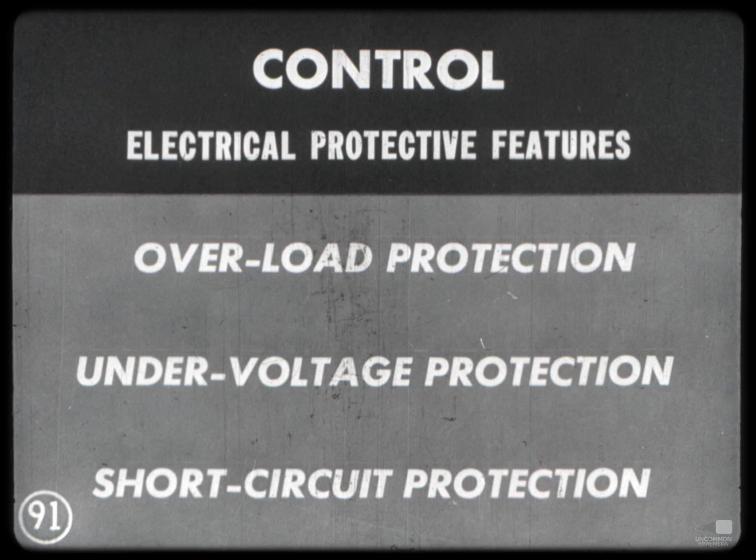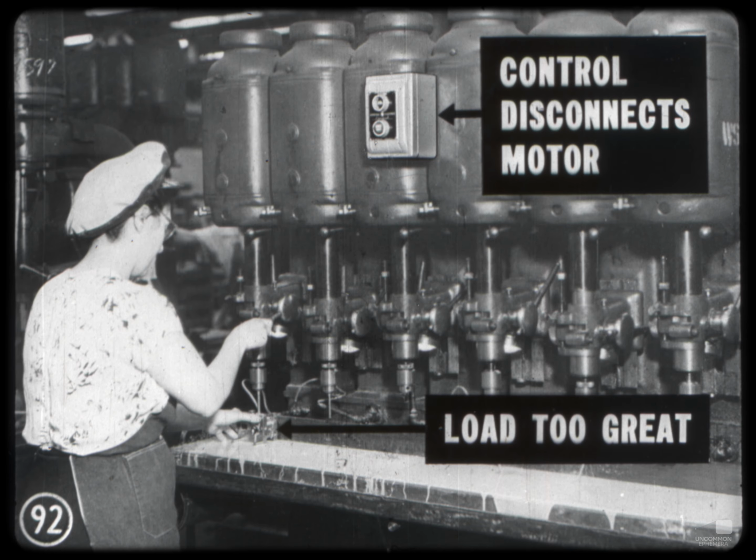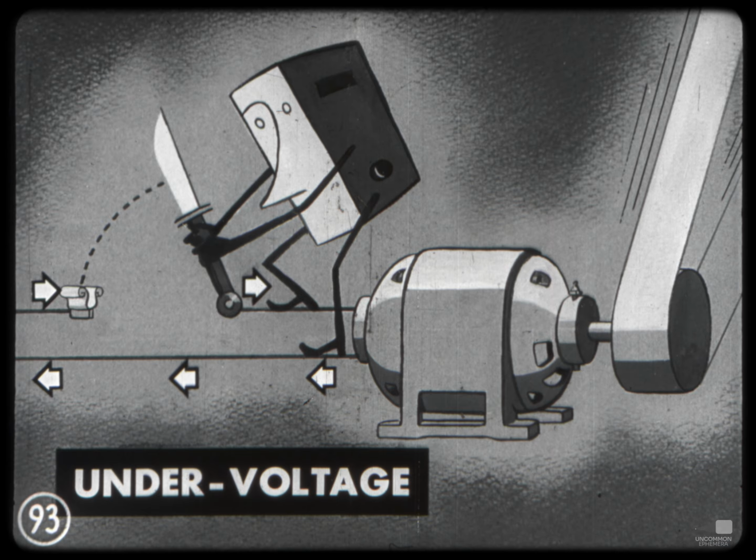With any job, control can provide electrical protection for the motor through overload protection, which every motor needs, under-voltage protection, which should be specified when needed, and short-circuit protection. On this drill press, for example, if too great a load is applied, the control automatically disconnects the motor so that an overload won't damage the motor. Generally, motors are designed to allow for small voltage variations. Yet, if there's a chance the supply voltage might fall below a proper operating level or fail entirely, under-voltage protection should be provided to open up the circuit and prevent restarting without positive action by the operator.